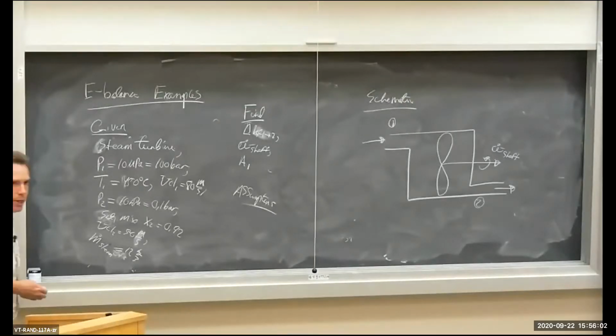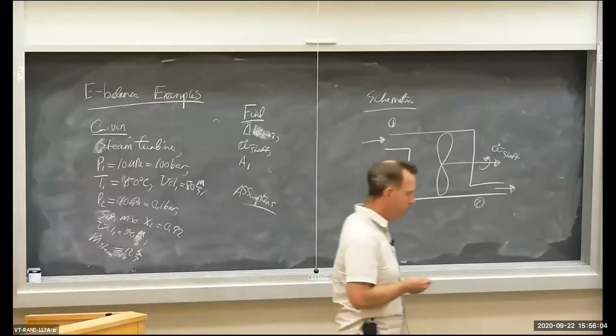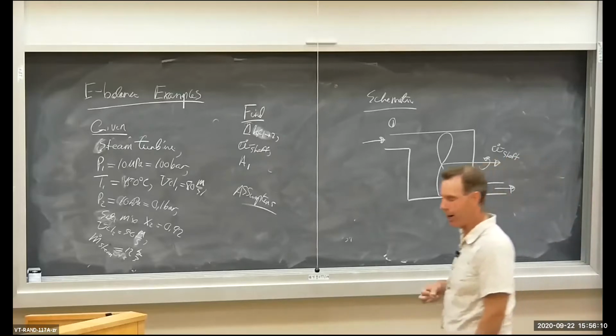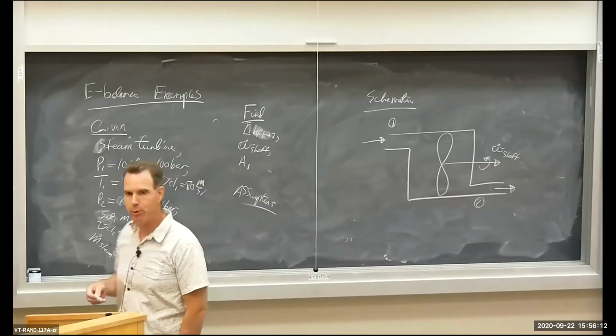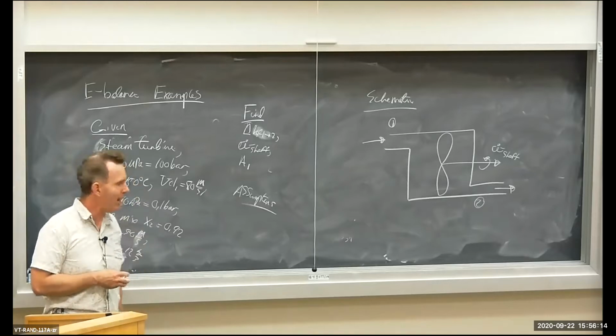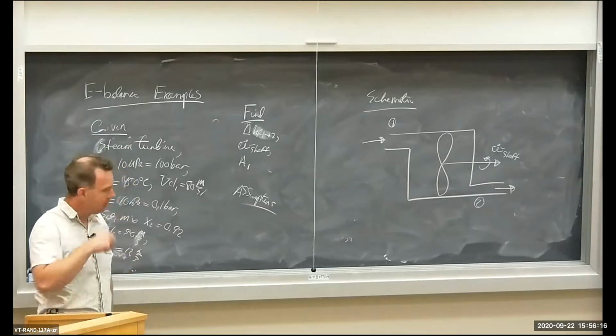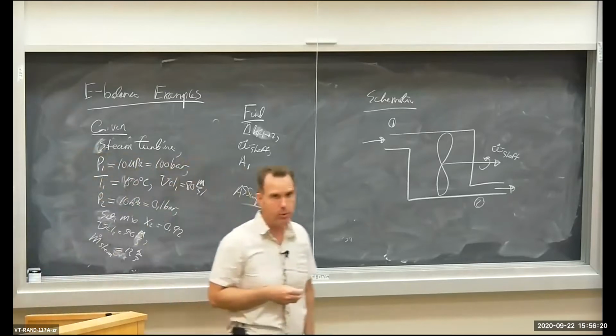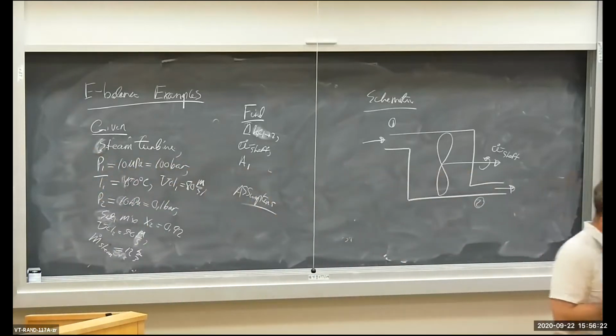All right, let's go through and do another example here. Instead of having an air nozzle, we now have a steam turbine. Remember, a turbine produces power, or shaft power in particular. So it works off of steam, not air. So obviously we're going to be using steam tables and saturation tables to do this particular problem.